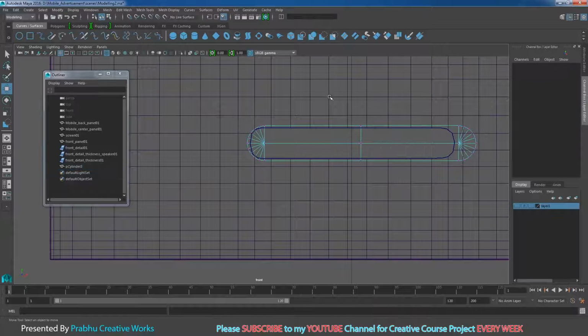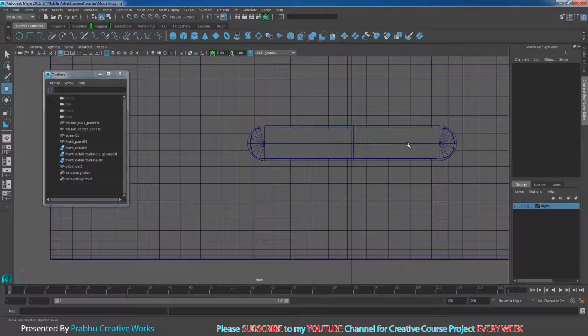Right click and choose vertex. So I will select all these vertices over here. So I will move a little bit inside. So I will move this one to the center. So right click and choose object mode.